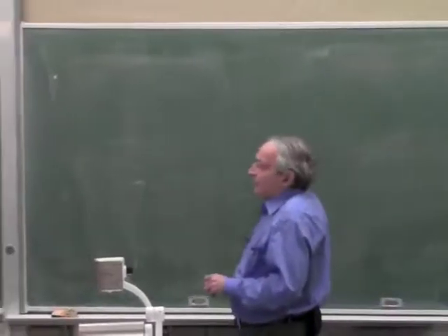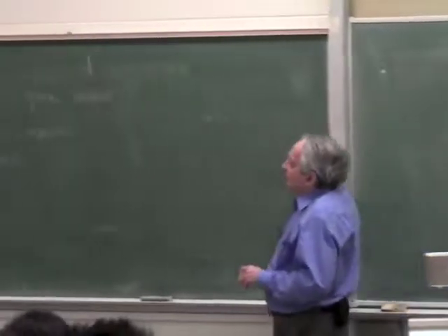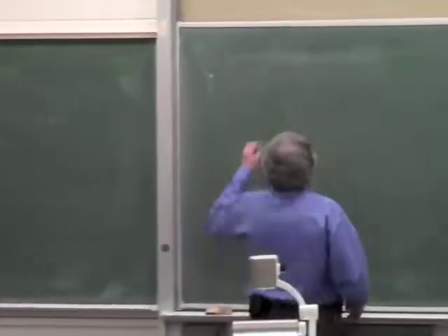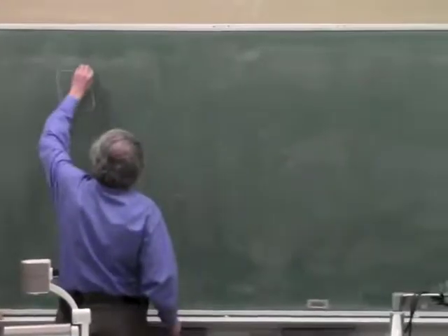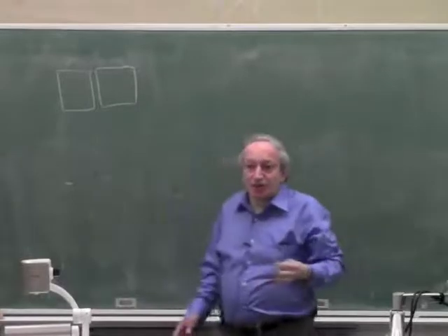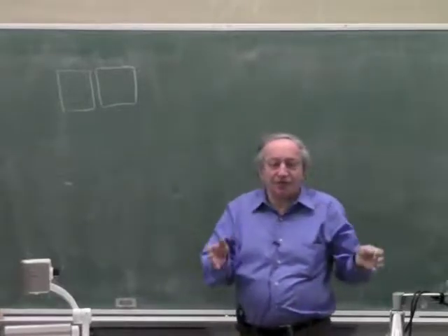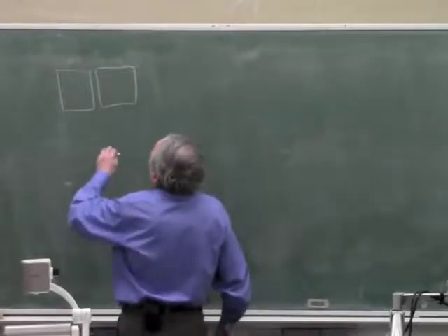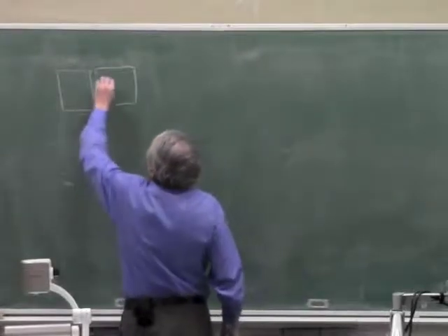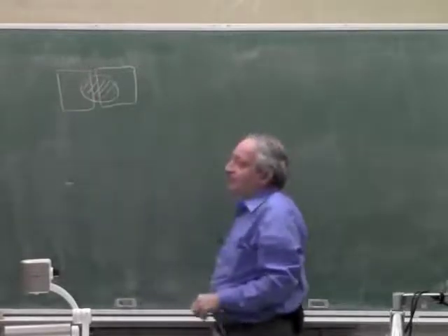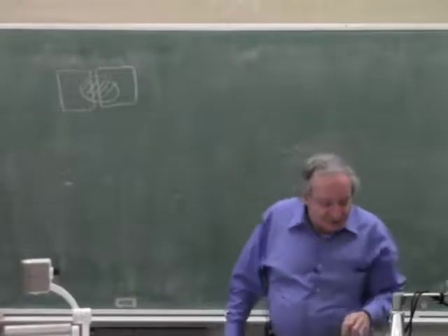But anyway, the most basic type of optical position sensor is you take two photodetectors. A photodetector is just a piece of PN silicon junction, like a photocell. And you take the difference between them when a spot of light hits them. So this is a spot of light, say from a laser pointer.